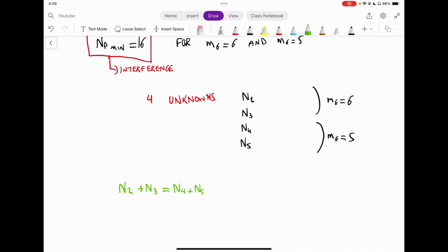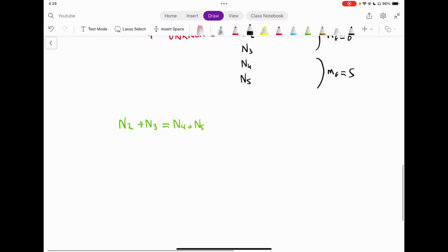So if you remember, your compound reverted gear train looks something like this. We have gear 2, which is going to be a big gear with a pinion 3, and pinion 3 is going to be connected to gear 4, and gear 5 is going to be a smaller gear. This axis is going to be aligned with, sorry for the scale, it's not perfect, but you get the idea. So 2 and 5 would be aligned with each other, even though they would be on separate axles,